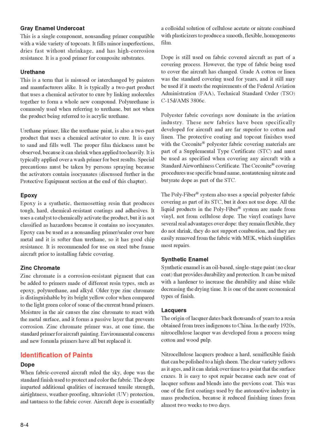Gray enamel undercoat. This is a single component, non-sanding primer compatible film with a wide variety of topcoats. It fills minor imperfections, dries fast without shrinkage, and has high corrosion resistance. It is a good primer for composite substrates.